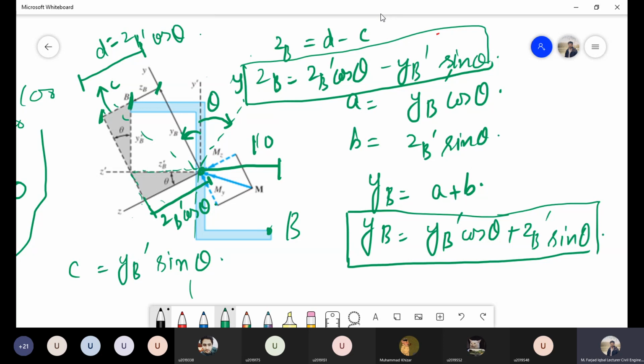And if you have a counterclockwise orientation, then you can substitute the positive sign with the angle. So the conclusion is that you have fixed your sign convention. If all your quantities come according to this figure in the question, then you substitute them as positive. And if anything deviates from it, for example the y distance or the z distance, then you have to substitute the negative sign with that particular parameter to get the correct answers for these inclined distances.